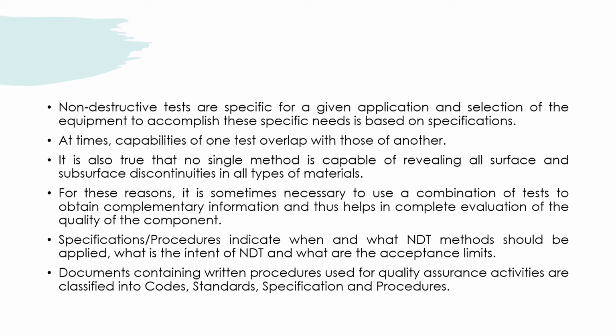Specifications or the procedure indicate when and what NDT method should be applied, what the intent of NDT is, and what the acceptance limits are. The documents containing the written procedures which are used for quality assurance activities are classified into codes, standards, specification and procedure.